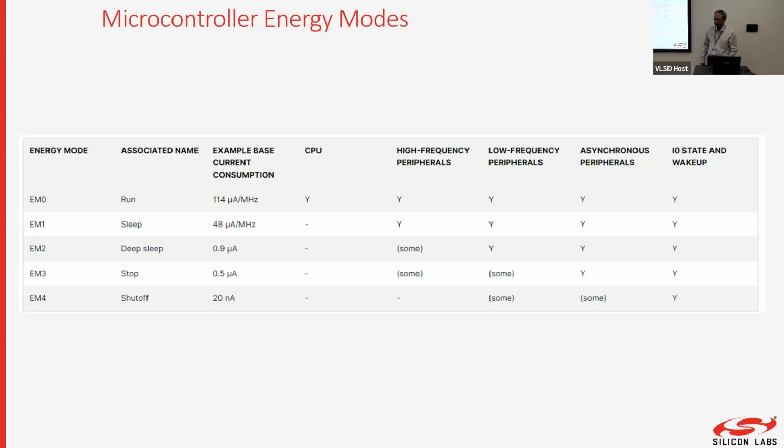So if you look at all of those, and as students, you do a project which is more like a product, you will find yourself suddenly more confident about a lot more things than you were if you just wrote some software and made it work. And that includes using these energy modes, understanding at this particular time which energy mode is best for me because this is what I want to do, and putting it in your program flow. So a lot of research has gone into microcontrollers, and they have done the best they can in providing the energy modes, and it's left to the embedded firmware developer to use those energy modes the best possible way.